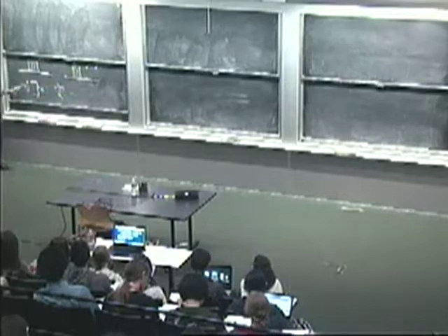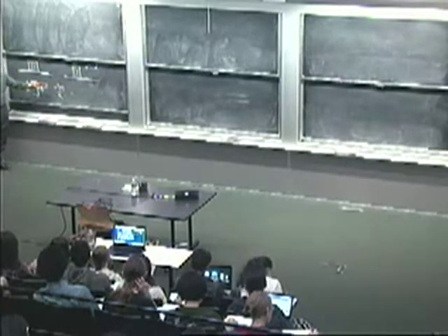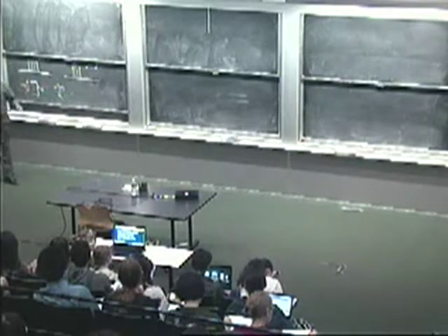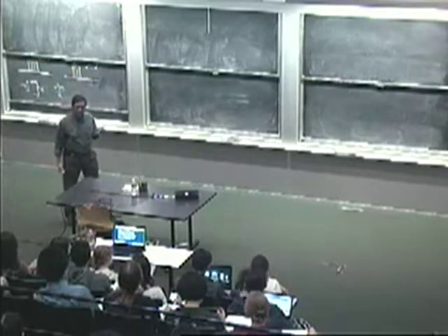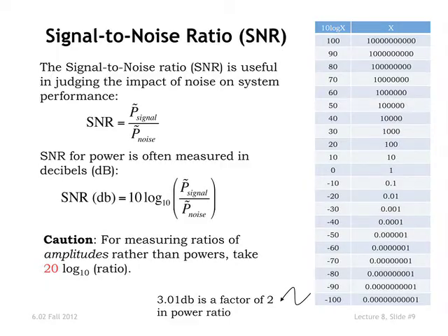So people start to think of the square of a quantity as power. In the continuous time domain, that's very natural in signals that come from physics. And that terminology has just been carried over to this kind of discrete time setting. So when people say power, they mean the square of the signal, right? It could have been called something else.